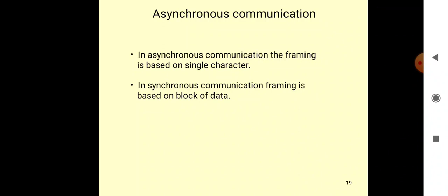The stop bit leaves a line or channel at binary 1, and the start bit always returns a binary 0. One extra bit, called the parity bit, will be there before the stop bit. The parity bit is used to control errors. So this is all about the asynchronous type of transmission.